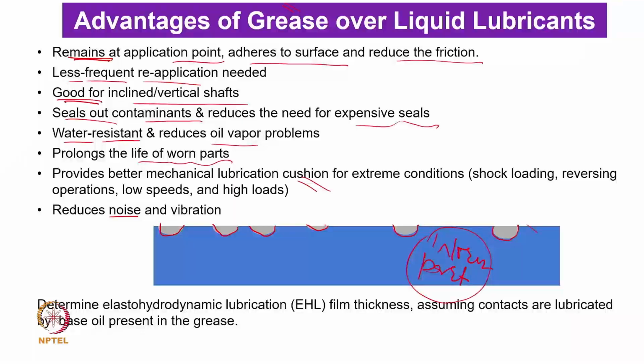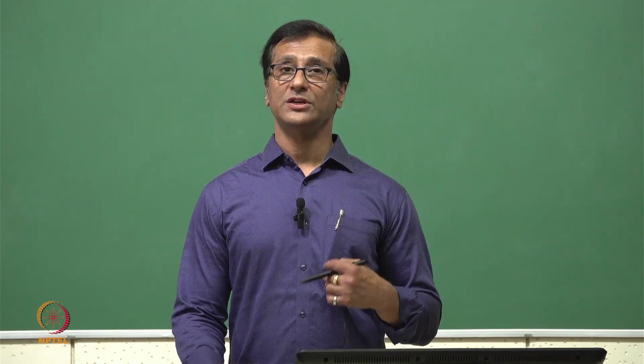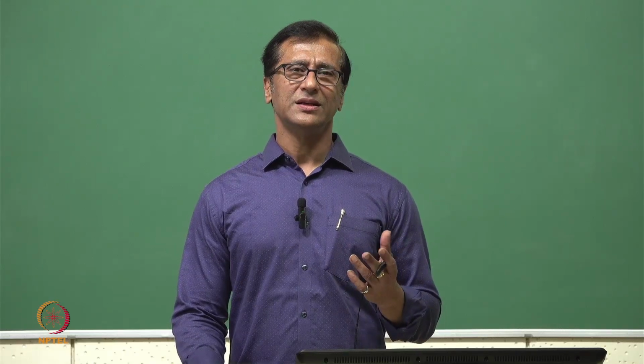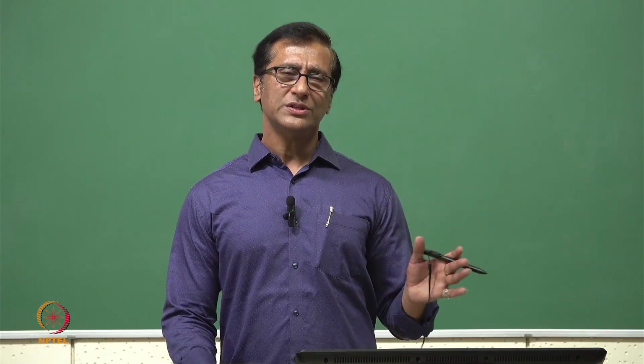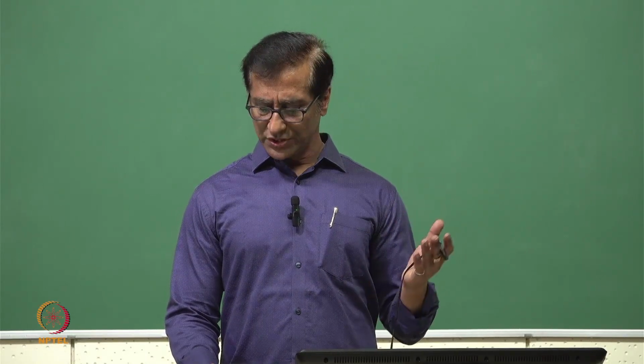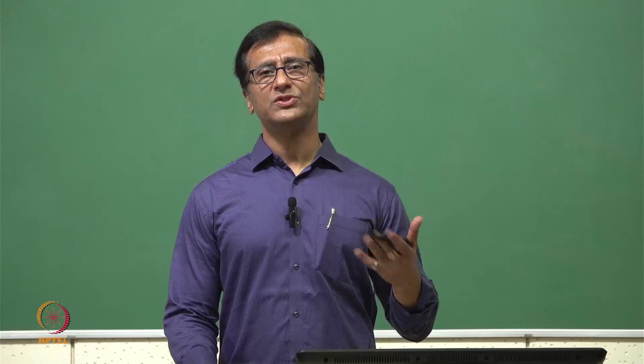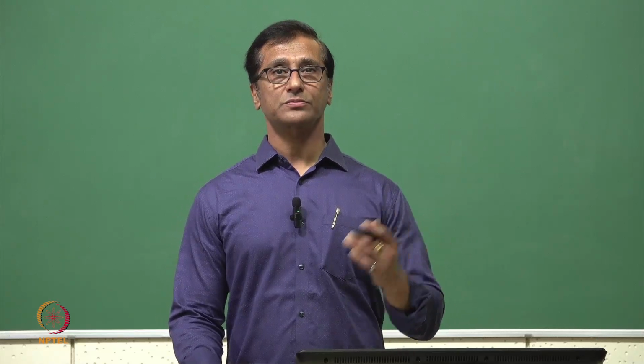However, one more thing is that we were talking about EHL. We want to establish elastohydrodynamic lubrication with grease, and more or less, whenever we are using grease, the elastohydrodynamic lubrication mechanism is established. To some extent, it can go on the lower side, a partial elastohydrodynamic lubrication mechanism, but in this situation, we need to establish some equation related to film thickness.